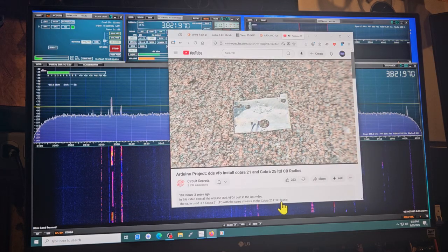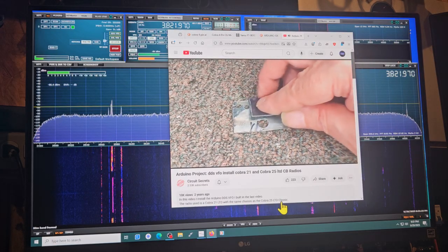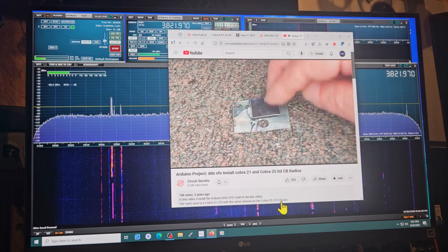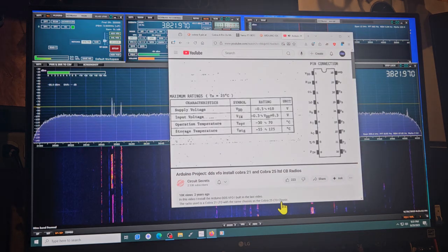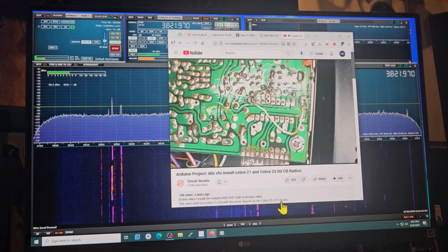Next, the board had to be modified to make it ready for the VFO. Many parts could have been removed, but I tried to keep the installation as simple as possible with the fewest modifications possible. I will start from the PLL chip where most of the modifications are made. This is the pinout from the datasheet of the TC9106BP. First, I had to locate the output to the VCO and cut the trace. This is just a precaution to ensure the VCO does not seek and generate excess noise on the power buses.